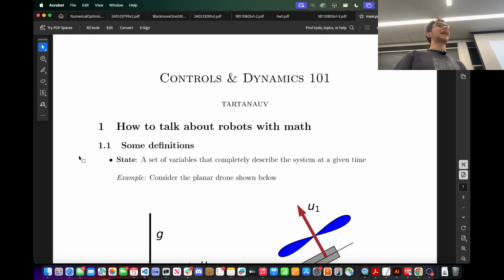And so at a high level, we have a vehicle that has some actuators on it, and our particular actuators happen to be underwater thrusters. So pretty similar to how a drone has propellers. Our thrusters exert force on the body, and we want the robot to move in certain ways. And in order to do that, we have to use a controller and develop guidance and control laws.